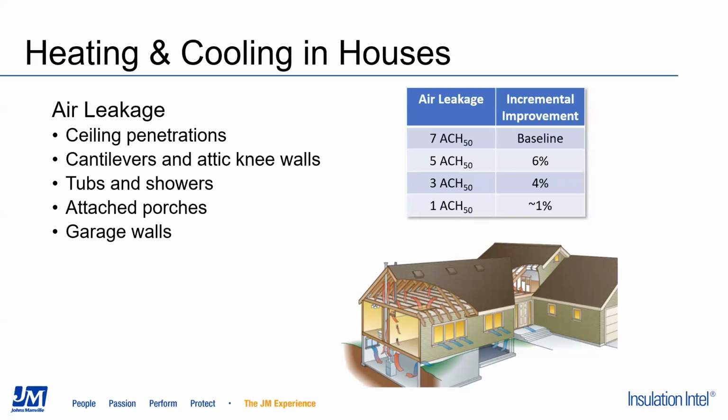So the best opportunity to prevent air leaks is in new construction when the home is built. And the list on the left side of the slide are the big holes, the really critical holes that it's important to have sealed, both from an energy perspective and to protect the indoor air quality of the house. So first off, ceiling penetrations.